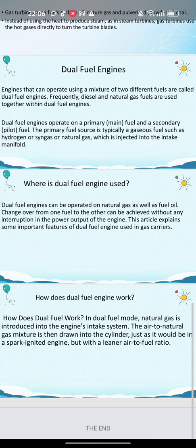It has a very high power to weight ratio compared to reciprocating engines. Steam turbines are suitable for large thermal power plants. They are made in various sizes up to 1.5 gigawatt, 2 million horsepower turbines used to generate electricity. Steam turbines have greater reliability, particularly in applications where sustained high power output is required.